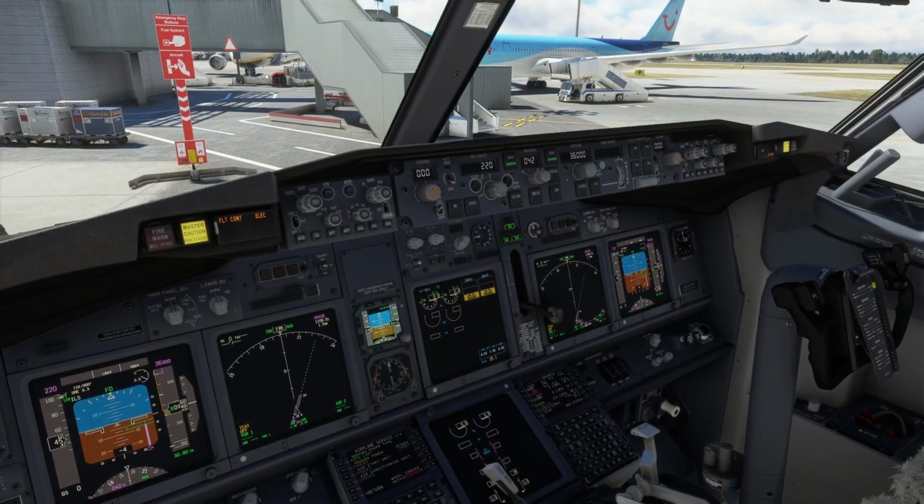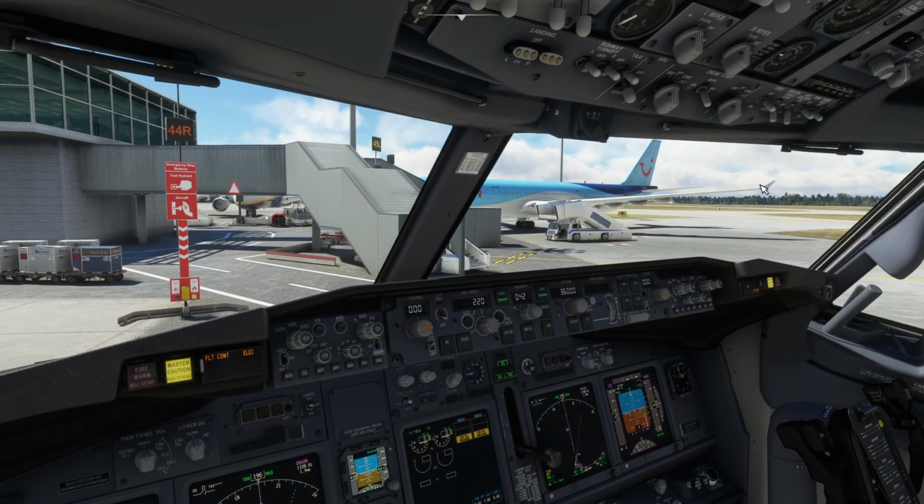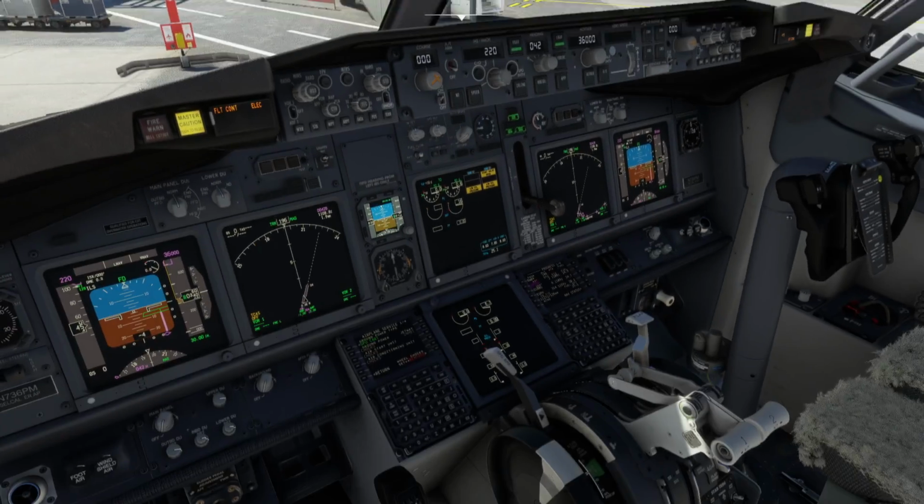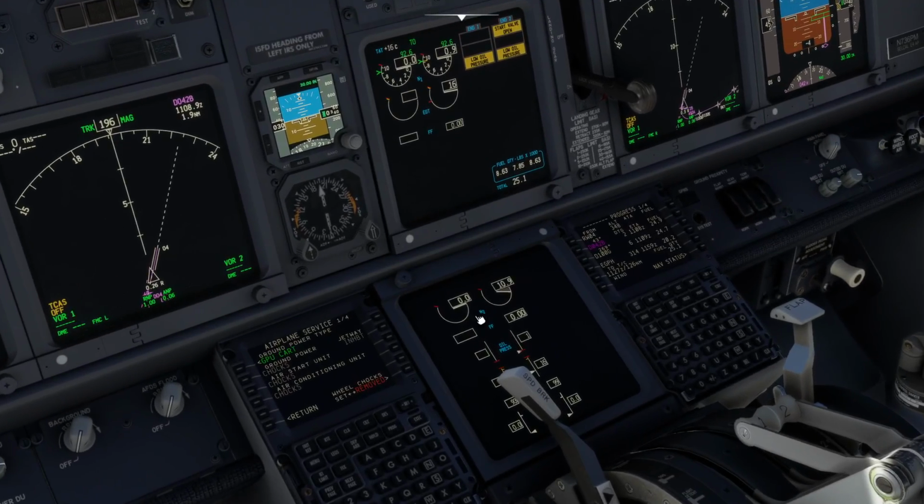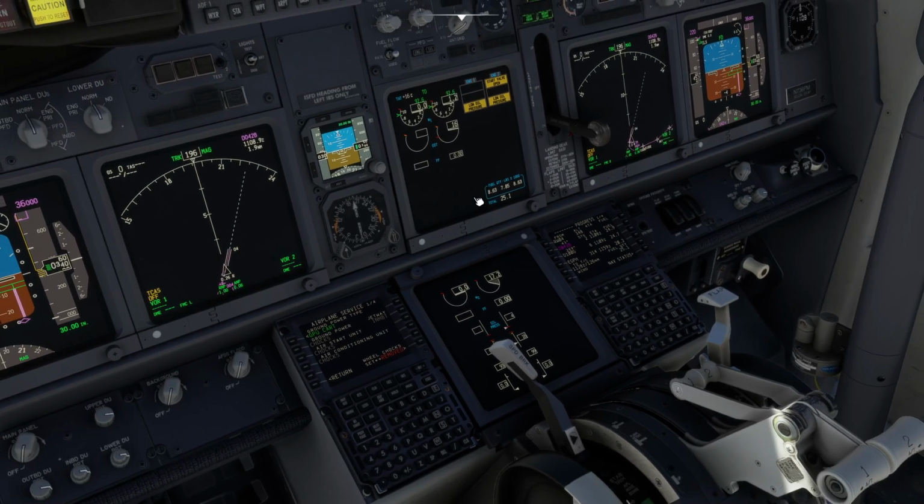Okay, so how do we start the engines? We turn the starter system for the engine number 2, or the right engine, to GRD. We choose an ignition system, so we can use left or right. So we'll go matched with engine side, it doesn't matter. Go for the right engine, and you can see the N2 speeds coming up. So that's the compressed air spinning up the gas turbine.